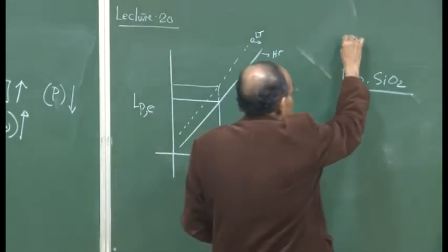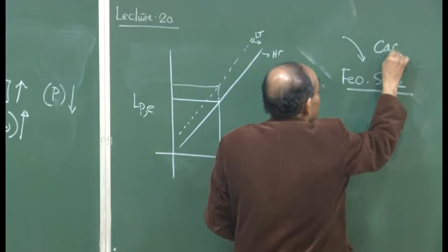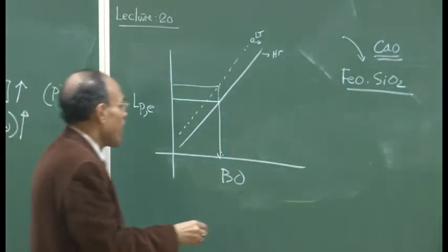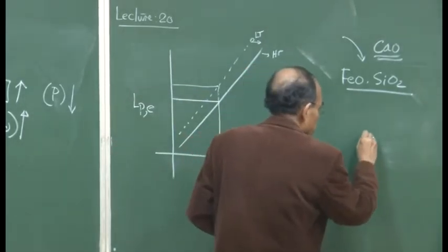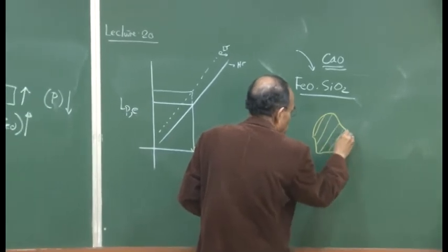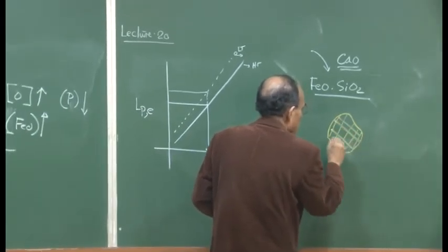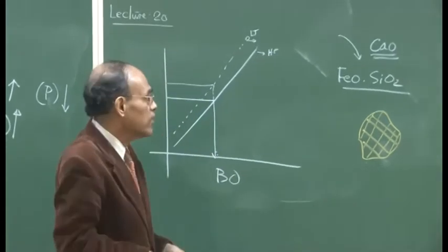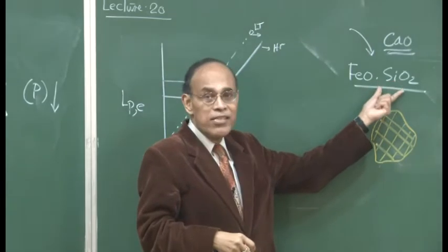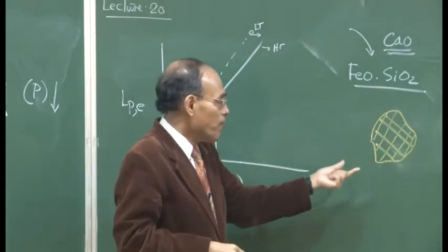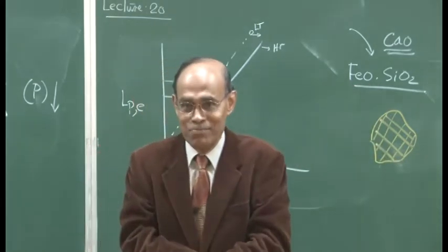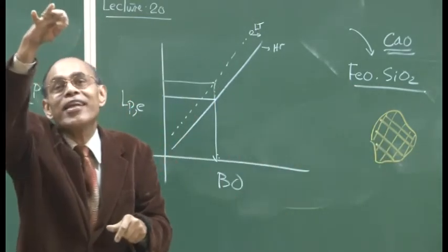Now, onto this you are adding lime. In steelmaking you do not add limestone, you add lime. So, let us look at the lime particle. This is my lime particle that you have added. These are all oxide phase silicate, and this is CaO; they are both much lighter than the molten hot metal. So, they are going to remain at the surface of the steel.